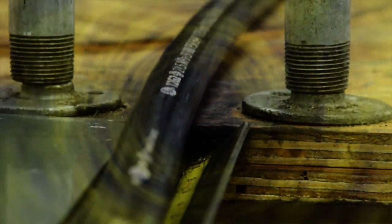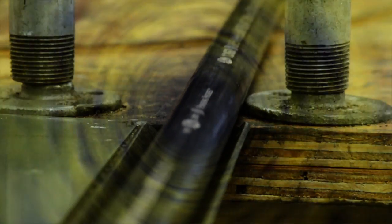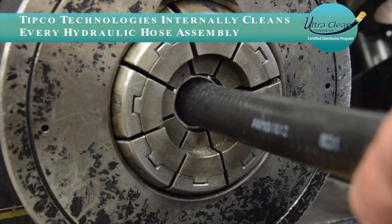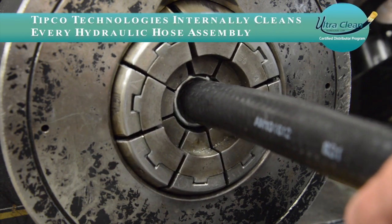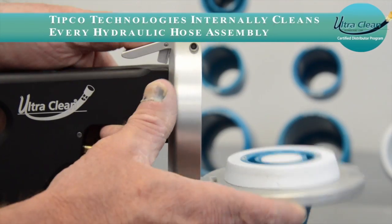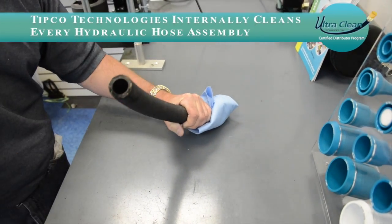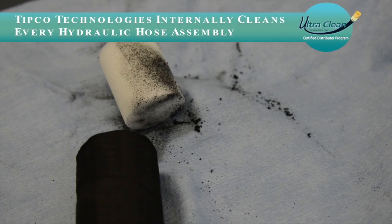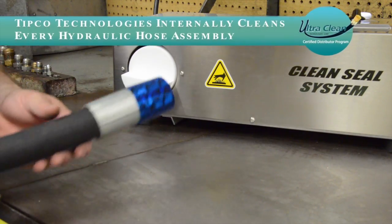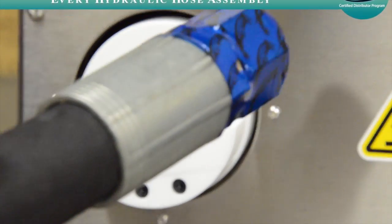But what happens to clean oil when it travels through newly installed hoses and tube assemblies that have not been cleaned? The particles of contamination from the cutting, crimping, bending, and flaring process create a problem that will cause premature wear and system failure. It is imperative to protect your equipment from hydraulic contamination. Premature wear and system failure can be greatly reduced by the installation of clean hose and tube assemblies. To see why, we need a better understanding of what contamination is and how it damages systems.